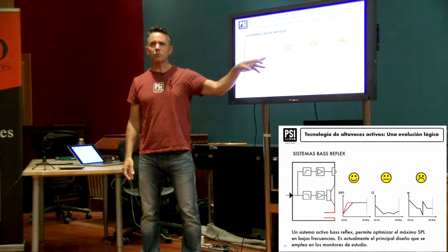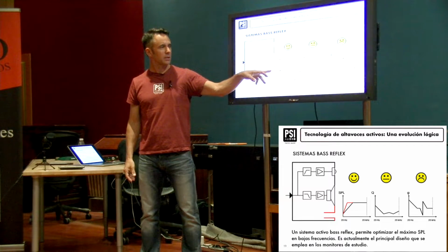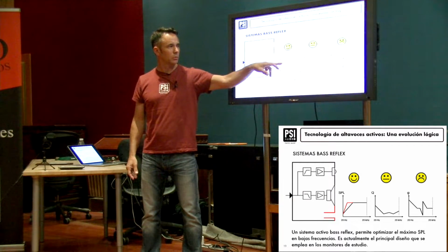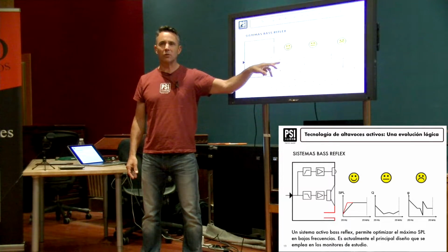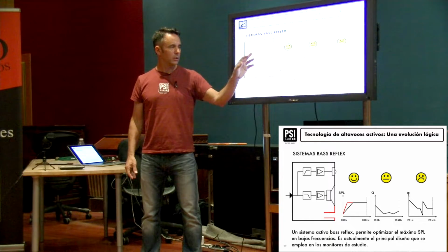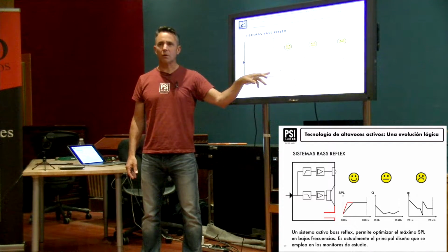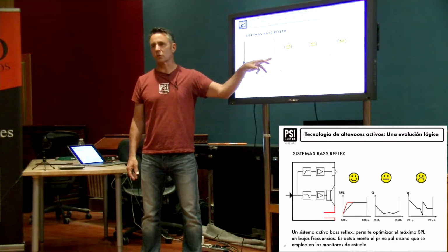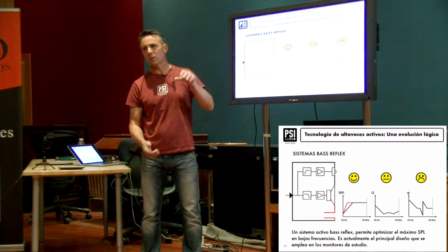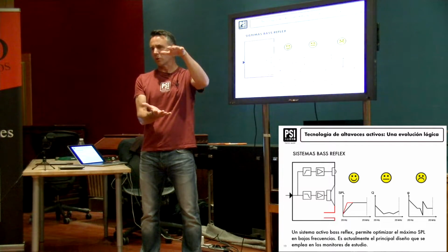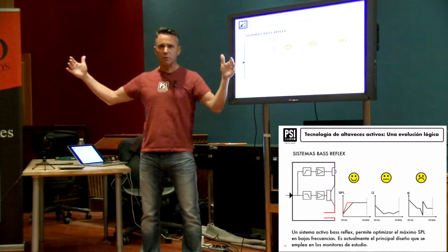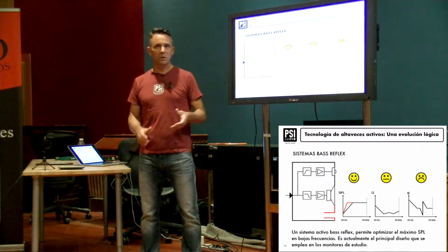So just as a basic rule of thumb, this allows us to use the energy from the back to extend the bandwidth down below, in the low end. If you don't have a ported cabinet or a bass reflex, you need 3 times the surface. So typically you'd need 3 times the amount of drivers. In studio monitors, you try and keep the monitors quite small, powerful, full range, so we use this quite commonly.